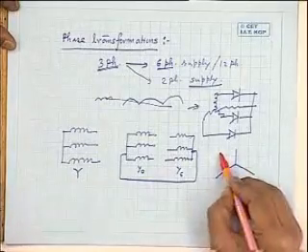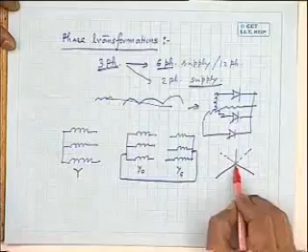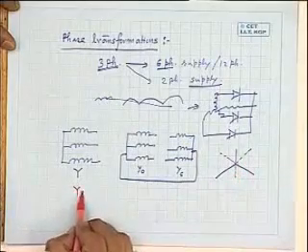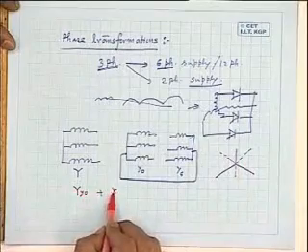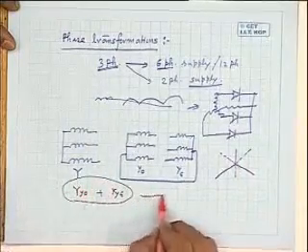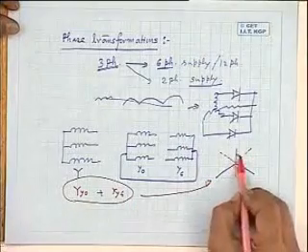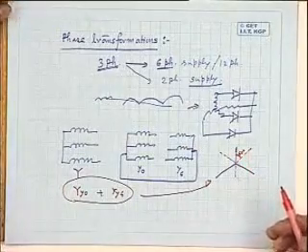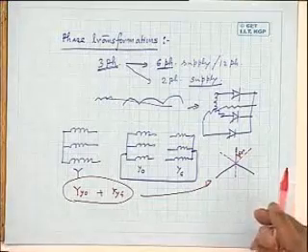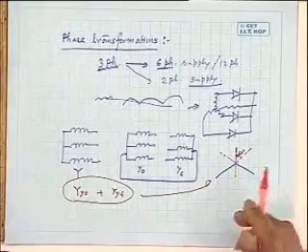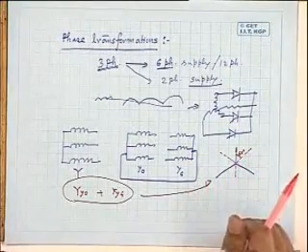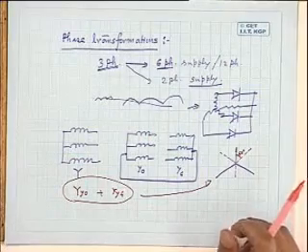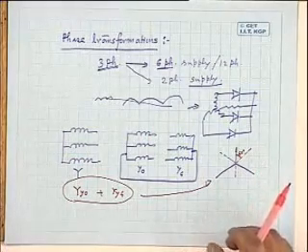So with respect to the primary, you will get one set of voltages like this. And the other set of voltages will be like this. So YY0 plus YY6, I mean the other winding, these two will give you this. And these angles will be 60 degrees. And it is a six-phase balanced system you will be getting. Can you get a six-phase balanced supply by other three-phase connections? Of course, some of you have come up with it. Okay, fine. What about other connections? Is it possible, whatever you have been taught?